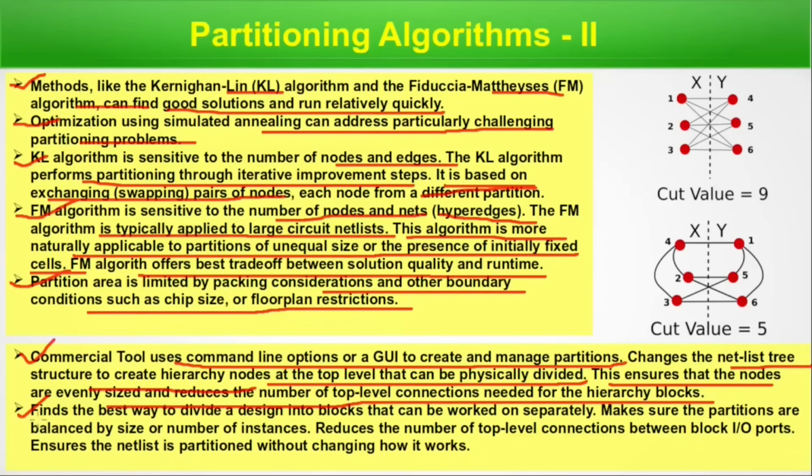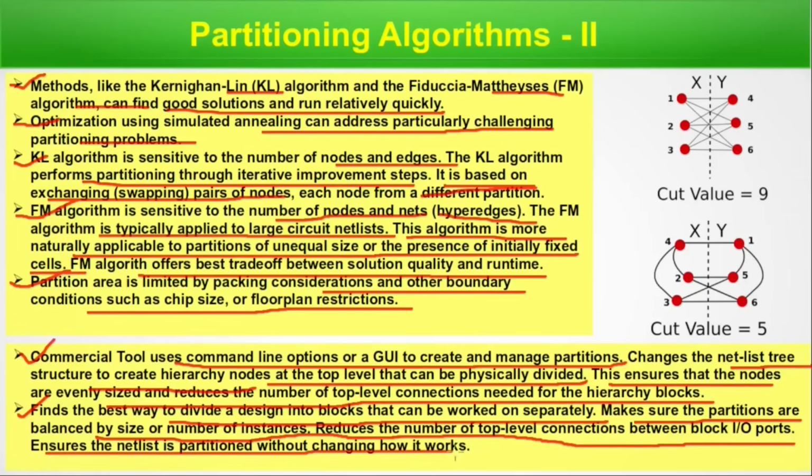They have that algorithm inside them. It finds the best way to divide the design into blocks that can be worked on separately, makes sure the partitions are balanced by size or number of instances, reduces the number of top-level connections between block I/O ports, and ensures the netlist is partitioned without changing how it works. We are understanding all these things with a small example, and R&D engineers in commercial tool vendor companies are putting all these tough algorithms inside the programming.